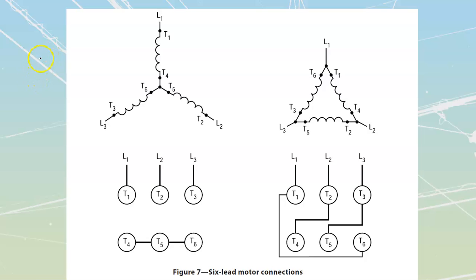That is going to be a 416/240 volt that I'm going to have off of that one. I'm going to put 416 ahead of the 240 because that designates this as being a 3-phase system. So that's my high voltage. This is going to be my low voltage.